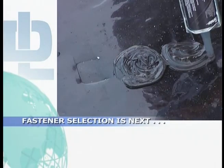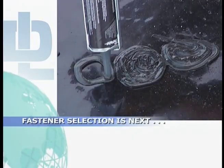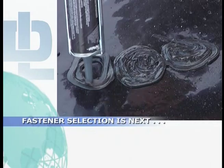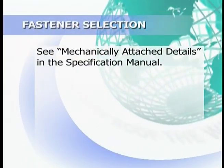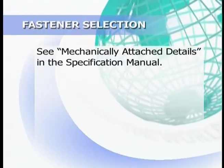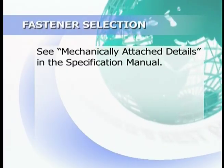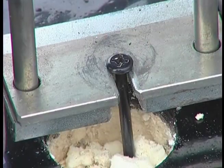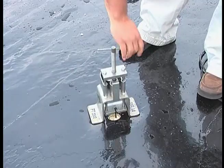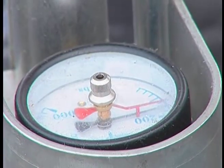With your core cuts and pull tests completed, you're ready to order the proper type and number of fasteners for your job. Refer to the mechanically attached details section of the specification manual for full details about fastener and plate requirements, use, ordering, and installation. Determining the correct fastener to be used for the job is crucial. You should understand the types and uses of the various Duro-Last fasteners and plates.